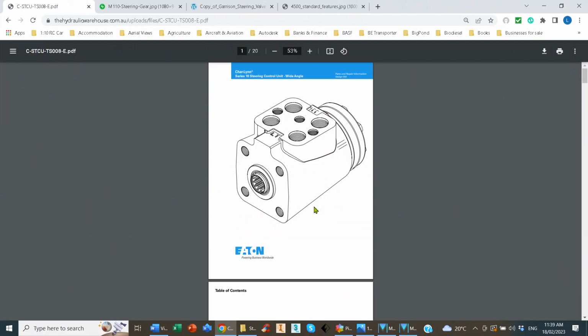The general assumption is that big vehicles can't be steered mechanically, and that's partially right. Obviously it's a question of scale, but there are options for mechanical steering for larger vehicles, and they come with power assisted options. The advantage of mechanical steering is you don't need an emergency steering system. Okay, the steering effort's going to increase, but everything is still there, connected, installed and operating. You just lost your power assist. So let's look at a couple of power assist options that there are.